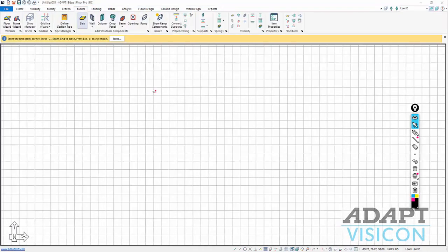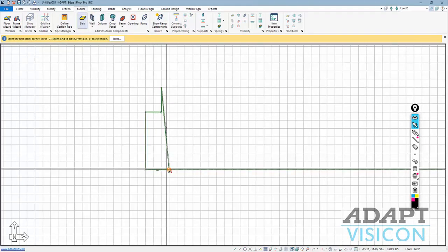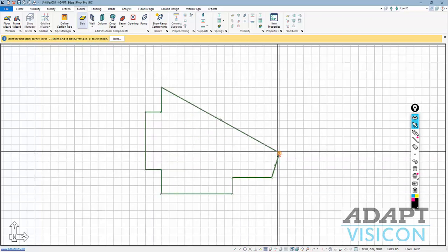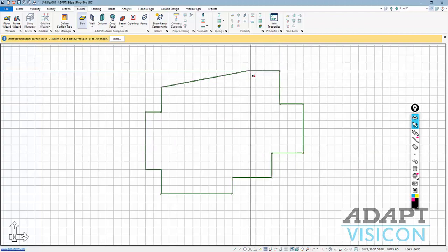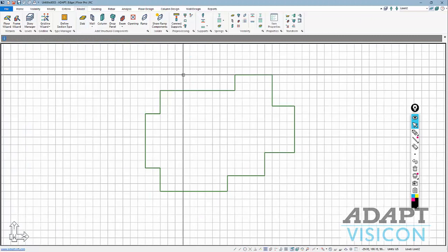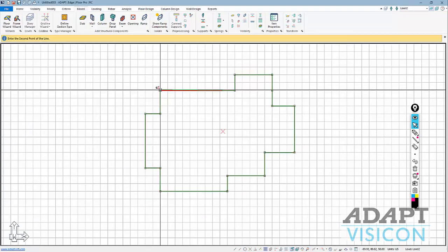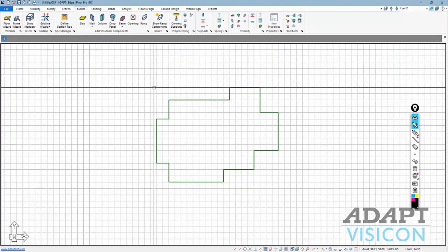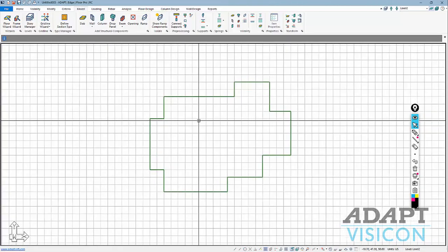Now I'll go ahead and just create a slab. So the slab, we're going to say, looks something like this. Okay, and once we have the footprint, we can define the thickness and the material property. We're going to use concrete 1 for the superstructure, and then if we wanted to assign a different concrete for the mat or the piles, we could also do that.